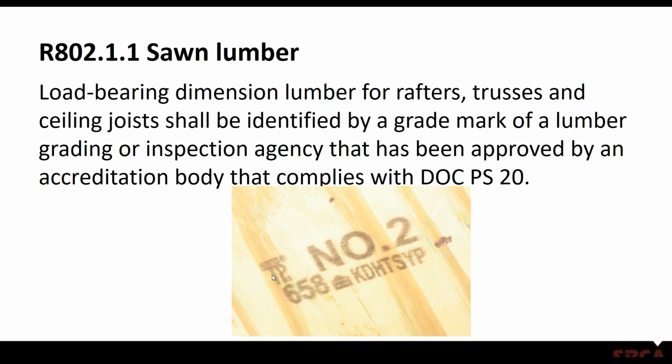In this case, TP is Timber Products. They are an accredited inspection agency. And this particular piece is Southern Pine. The mill number was 658, and its grade is a number 2. So that is a visually graded piece of Southern Pine lumber. The KD means that it was kiln dried